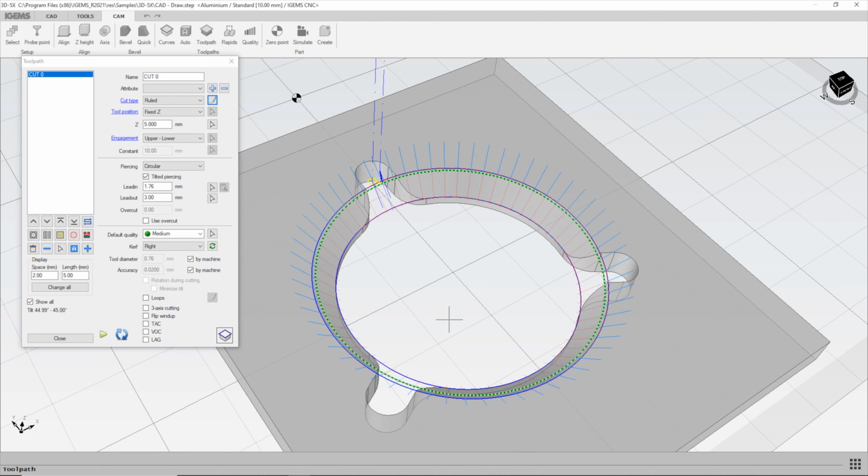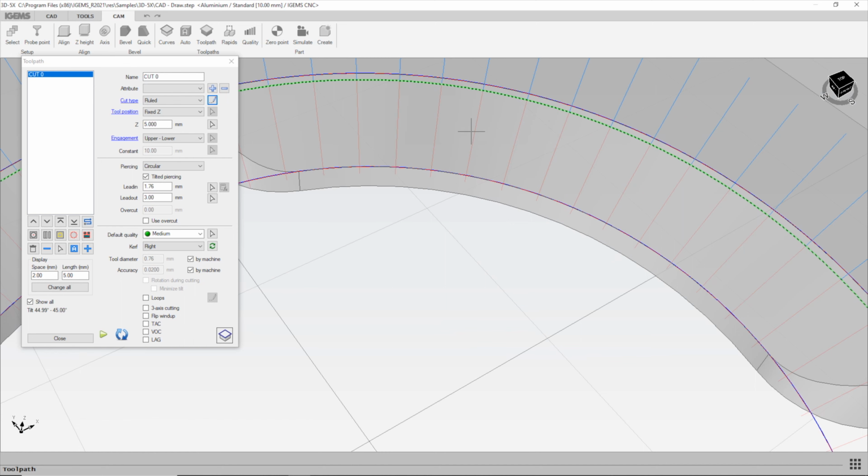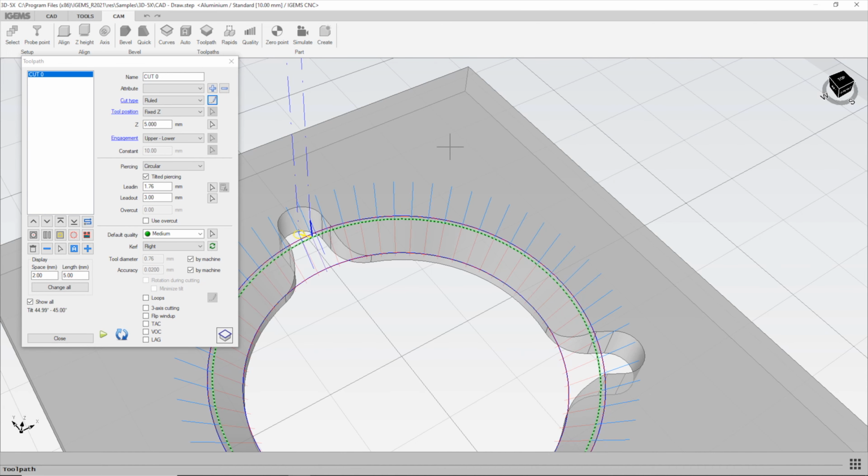But there's still one issue. This probably would have worked, but you see the red lines here? We calculate the cutting speed on this length. So we want to have these lines touching the table because this is still material here. So we want to have the engagement. Let's click on the blue text here and we see what engagement means.